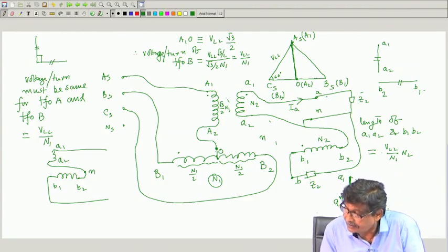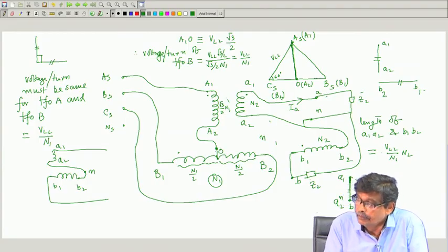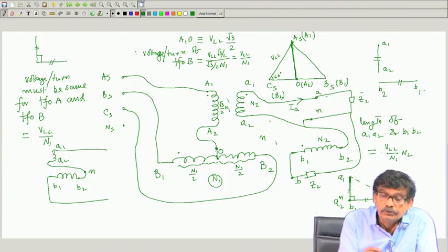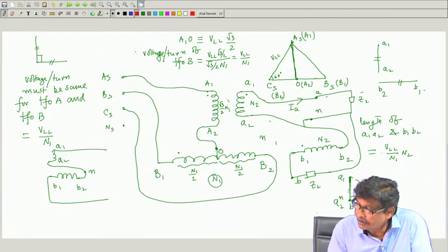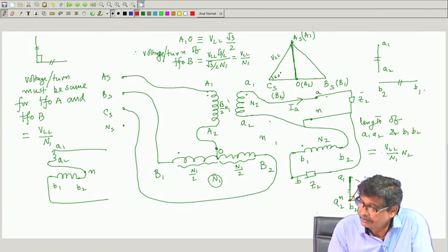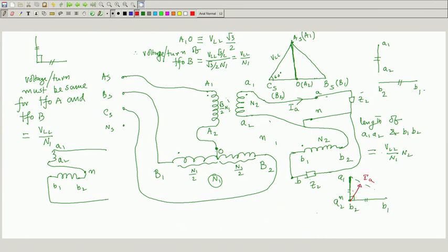So, I A here, depending upon the power factor angle of Z2, it will be positioned. So, I A may be there, this is I secondary. What is this angle? It is the power factor angle of the load, the A phase current I A.